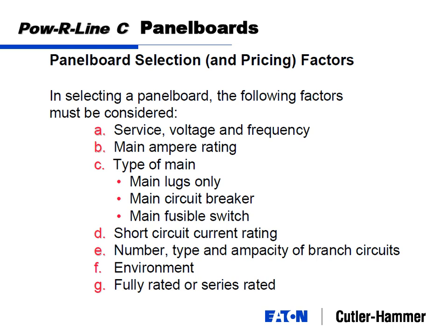Mentioned earlier, you can assume I'm putting a panel board in the wall, but we don't make all our panel boards for putting them inside here. You may want to put the panel board on the outside, in which case you'd need a NEMA 3R enclosure. Did you talk about enclosures yet? We know the wet location and dry location. Okay. And from our standpoint, NEMA 1 is the lion's share of what we do, mounted in an indoor enclosure. NEMA 3R mounted outside.